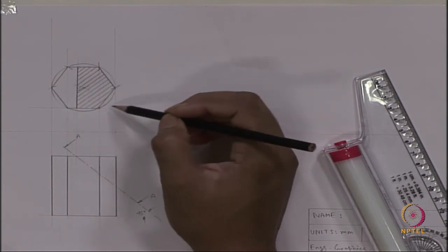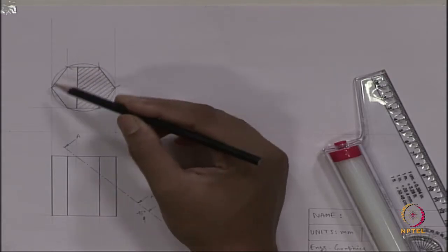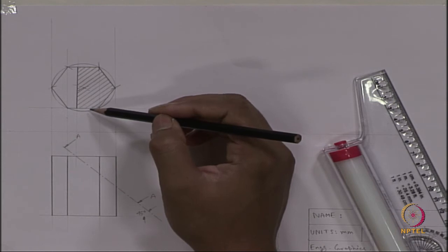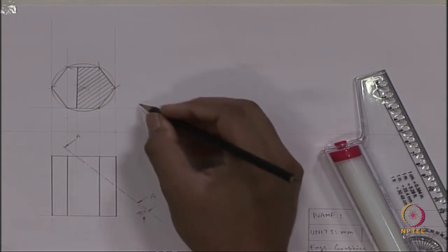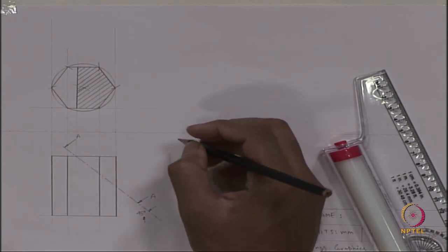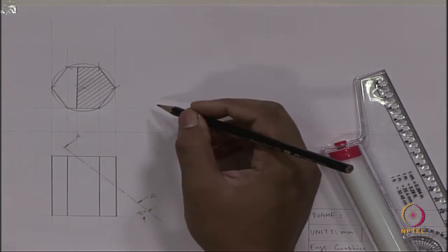In this case the top view will be the related view. So, when we draw the auxiliary view, we will take the dimensioning help from the related view, or top view, and other help like the positioning, like it will be parallel to the section plane, the reference plane, those kinds of help we will take from the adjacent view, that is the front view.